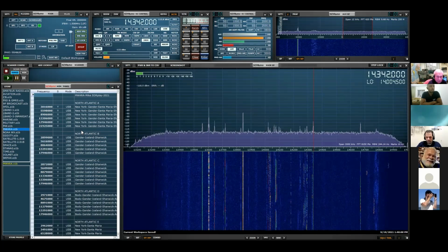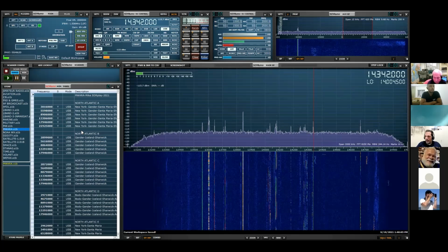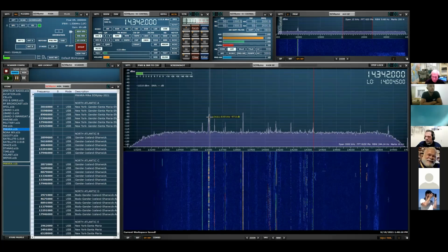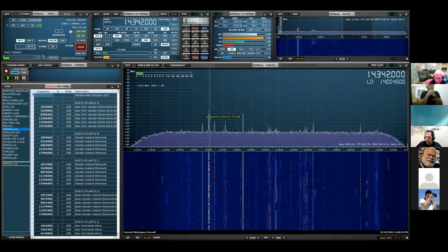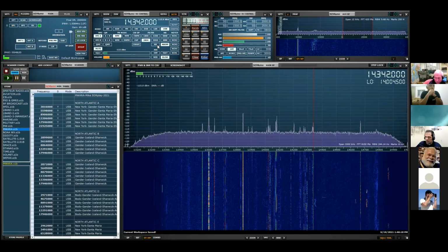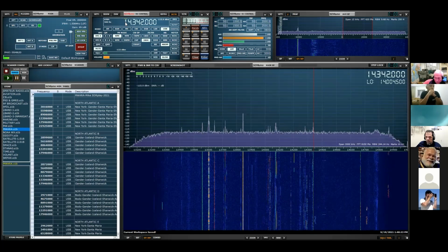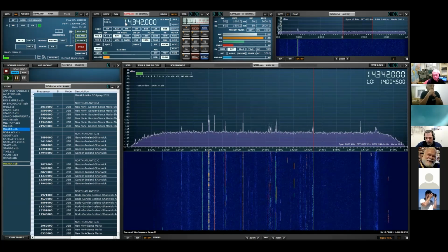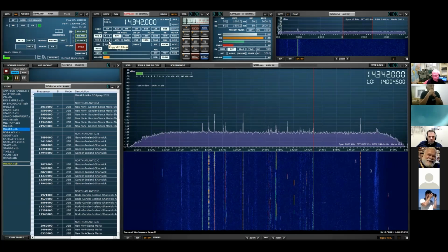Thank you, my pleasure. Hey, Mike, we got a question from Frank, KB4T, picking up individual 120 hertz spikes caused by power line interference. Now, the RSPs do not tune below 1 kilohertz, so I don't know if you're trying to get down that low, in which case you won't have success, or whether you're looking for harmonics of those, which do appear within the range. Yeah, you would see the harmonics once you get above 1 kilohertz, but if you're looking for 120 hertz, you're not going to get very far.